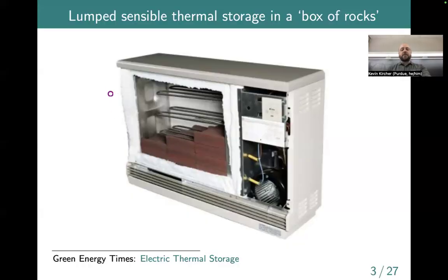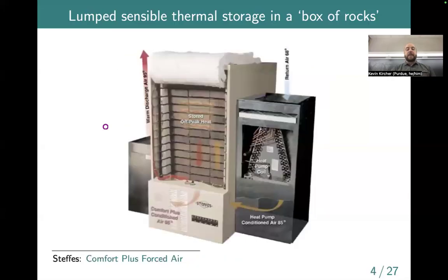So this, I guess, you'd call point source storage, in the same way that a mini split is a point source heat pump. We called it a point source heating or cooling source, meaning it's done at the zone level where people live, rather than in a central plant with heat or cooling piped or blown around. But you can also get a box of rocks thermal storage in a central configuration. This is a company called Steffs or Steffies. I'm not really sure how it's pronounced. But this again is a big insulated box of rocks. The white blanket-looking things here are thermal insulation.